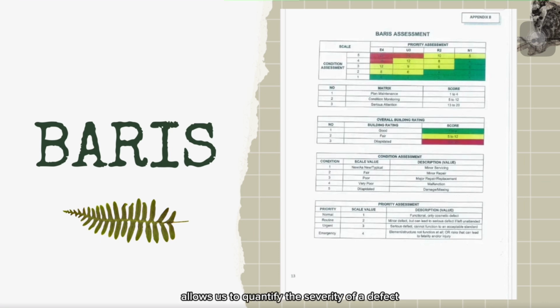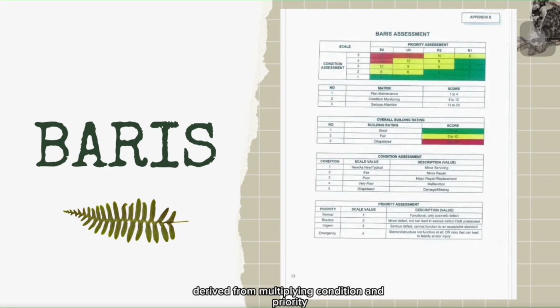Before we dive into specific defects, I want to highlight the BARIS table found on each sheet. This system allows us to quantify the severity of a defect using 4 metrics. First is the condition. We rate the physical state of the element from 1, which is good, to 5, critical. Second, priority. This determines how quickly a repair is needed, ranging from normal to urgent. Third, metrics. This is the score derived from multiplying condition and priority, giving us a final defect rating. Lastly, color code. Green represents low risk, yellow is medium, and red indicates a high-risk defect requiring immediate action. This data-driven approach ensures that maintenance funds are allocated where they are most needed.